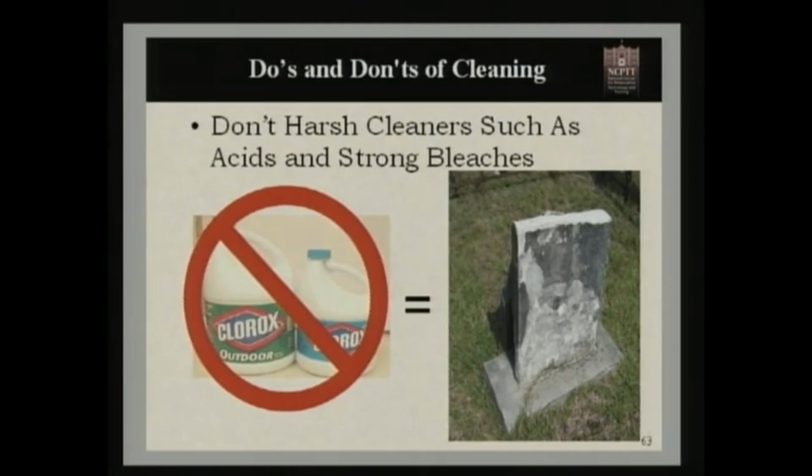And you can see how delaminated this stone is, how sugared it is, and that it's almost a complete failure because of this. We talked a little bit earlier, when we had that question from the audience, and thank you for that, about how this works by letting salt crystals grow inside the stone, which pushes the stone apart.